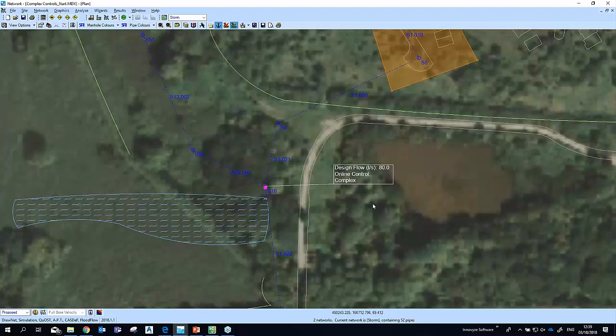What I'm going to do now for the design of the storage structures could be the process that Chris mentioned of iteratively going and opening up and sizing and having to balance this, so balancing the shape of my pond to make sure that I hit those cover levels or don't exceed those different head levels that I've specified already. And this can often be quite the complicated and scary bit of complex flow control design, getting the two working in tandem, the piece of storage and the flow control.